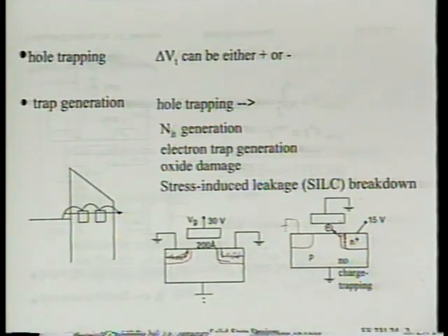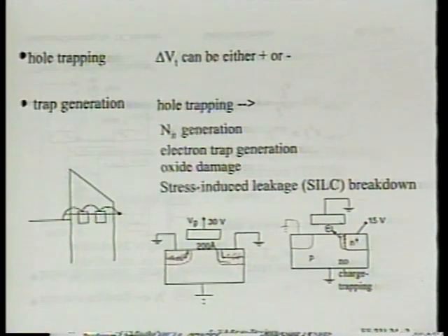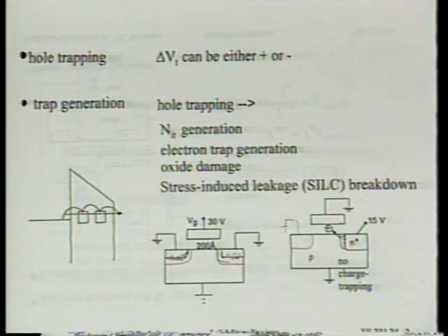Yes, please. Is it possible that the oxide breakdown starts because of GIDL? Because of GIDL? Yeah, GIDL. Not so much because of GIDL, except if you say GIDL then leads to the breakdown. So right now, let's not just consider the fine difference between what is GIDL and what is junction breakdown. I think we can all appreciate at some point there's a lot of impact ionization. That's what's called a breakdown, and that is the condition for the oxide to break down, because under that condition, a lot of hot holes get injected.